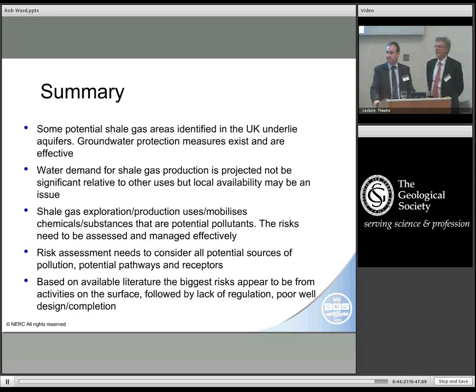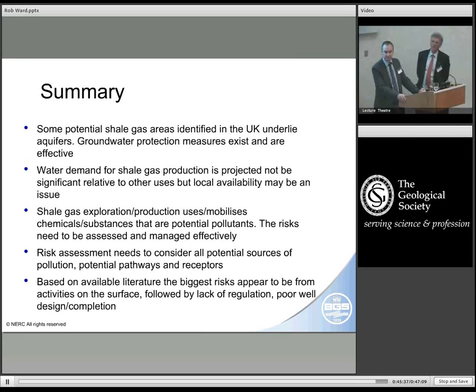Hello, John Hackett, Anglian Water. I'm very much involved with borehole construction, and I'd just like to understand, although we've got these policies of construction that are well established, whether it's time to look rather innovatively at incorporating monitoring devices that give us immediate responses to, say, pressure relief or casing failure, where Peter was alluding to immediacy of microseismicity and how it gives you an immediate picture. If you have the immediacy in terms of monitoring casing failure, because it does rapidly pollute aquifers, and then we would have to remediate for that.